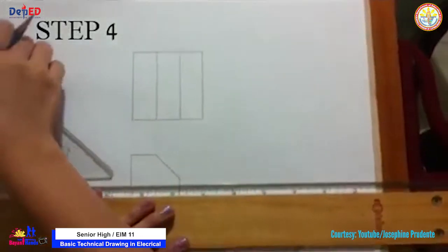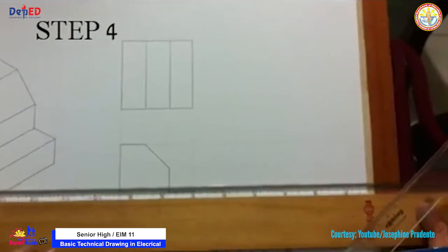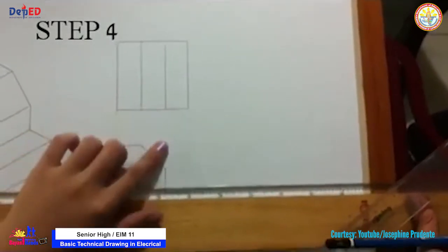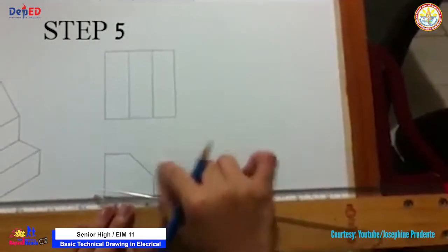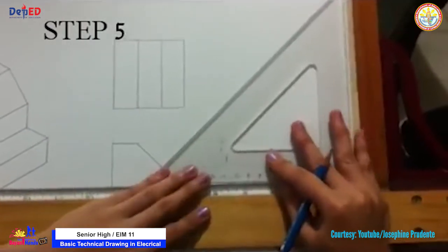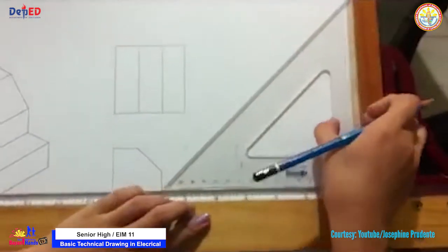Project from the top view back to the front view. Use the vertical projectors to fill in any missing feature in the front view. Draw a 45-degree projector off of the upper right corner of the box that encloses the front view.